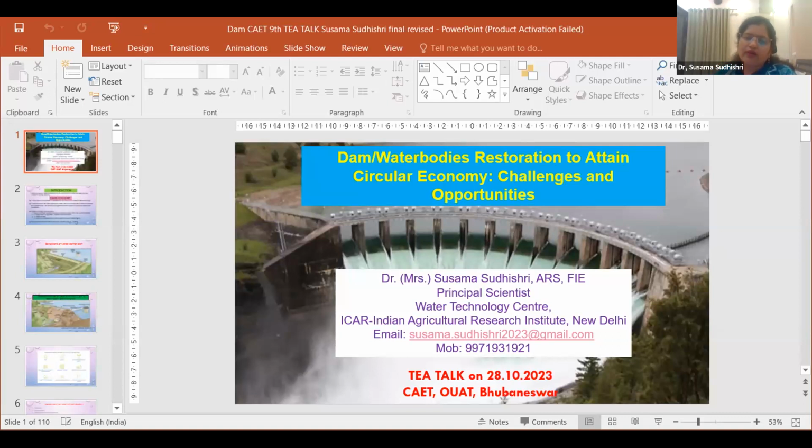Yes, sir, what I have already shown for Hirakud Dam, for desiltation alone, I have shown in one of my slides, it will take a minimum of 4 to 5 years. But again, the problem is where to divert that water. That is also a main problem in the case of large dams. But the main solution, so that it will not aggravate further, is the catchment treatment.